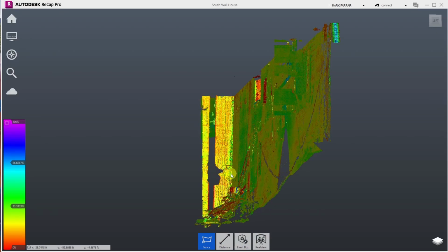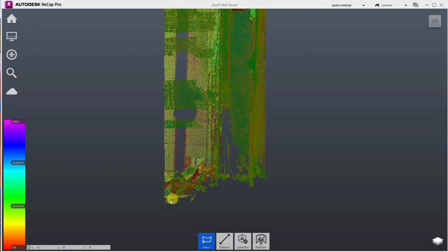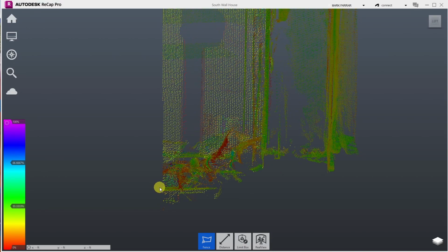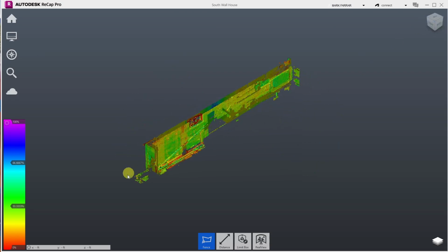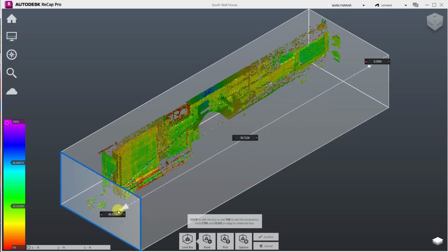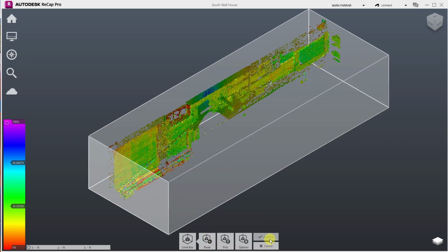Now, this wall back here, if I suck this in, I could probably turn it on end and then cut the pipes out this way, cut there, up, and over if this wasn't here. So to do that, I need to just come back to this again. Now I need to go to that corner because it has to face me to change it. Then I go to my limit box, hit edit, grab that guy, pull it in, see how it's gone? Boom, gone. Now I can't erase that stuff, so I hit confirm.